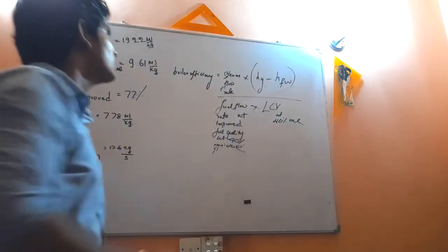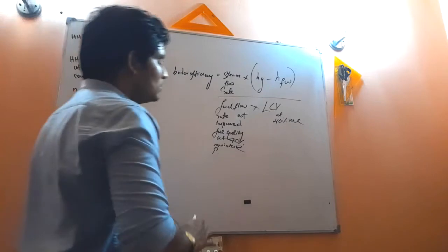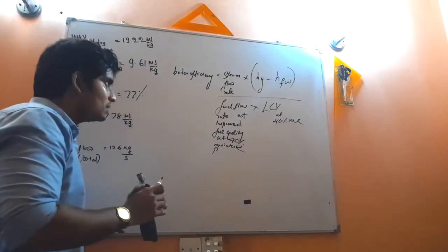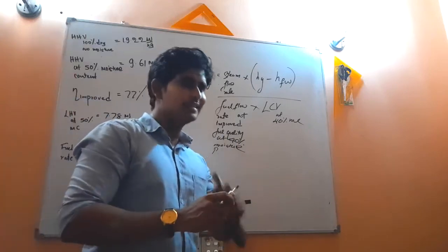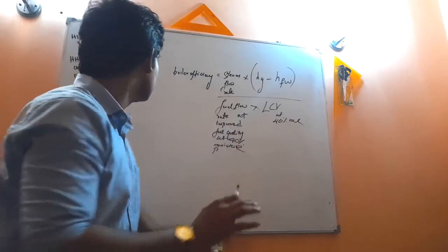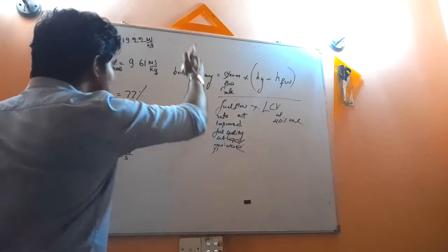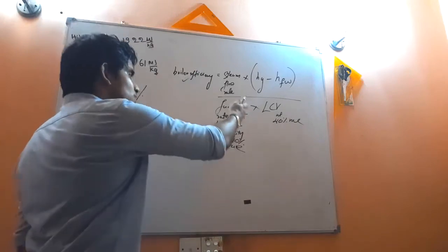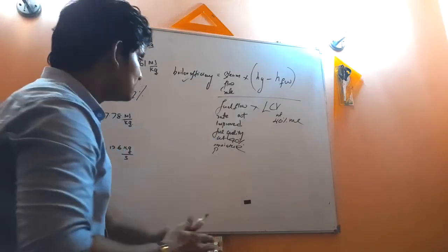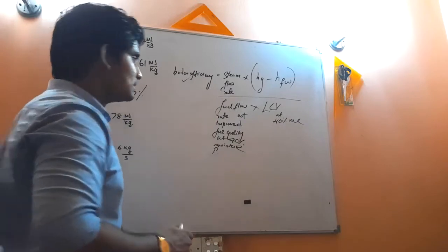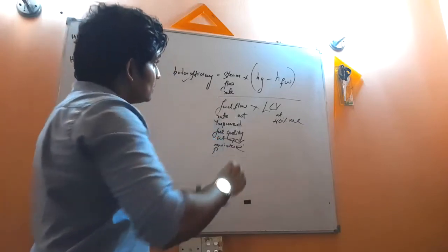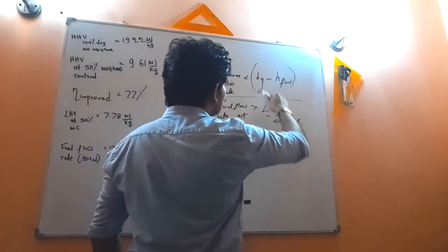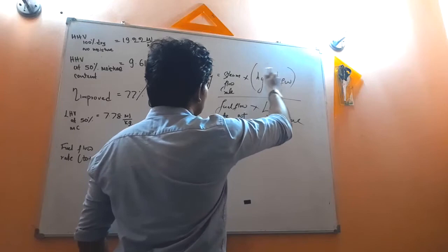So now this is the formula. Here our target is, now we know because of the dryer mechanism the fuel quality is improved and that has resulted in an increase in the boiler efficiency. That is part 1, right? We have evaluated there is an increase in the boiler efficiency. And the fuel flow rate we also evaluated based on the new moisture percentage, so that is also okay. Then the lower heating value is something that we have to find now. I will teach you how to find it. Then the steam enthalpy and feed water enthalpy we know.